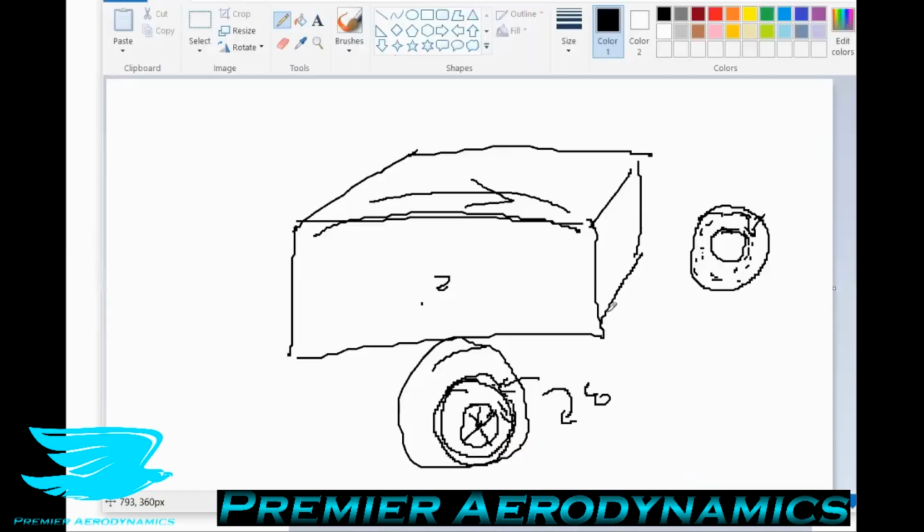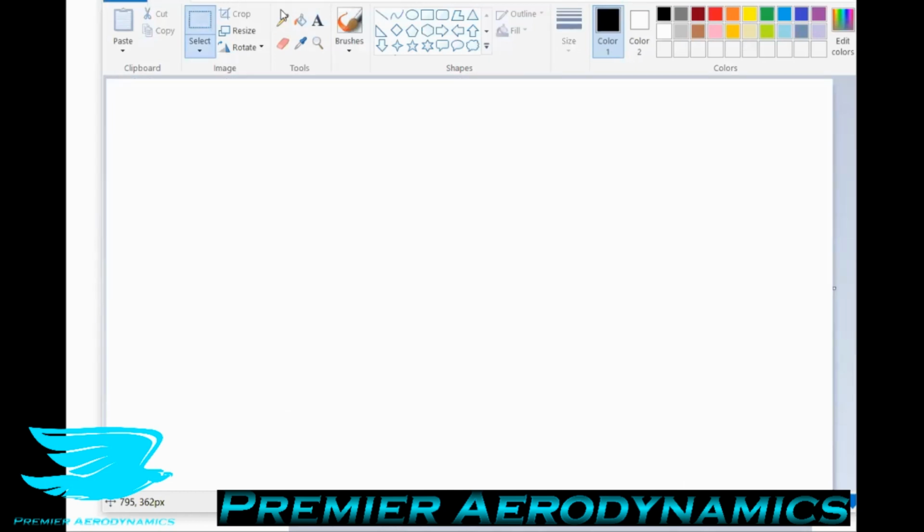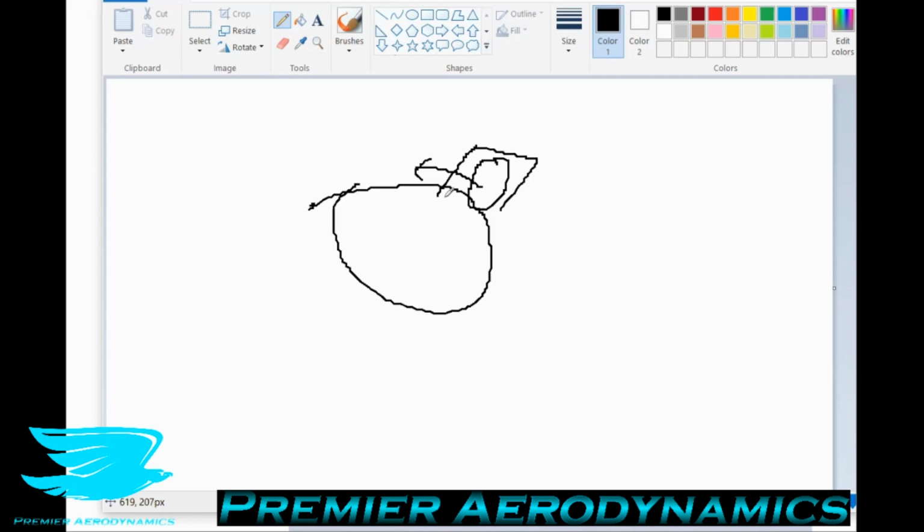So what is this? So far in this podcast, we've talked quite a lot about CFD methods, which it's good to know. So this Overset Mesh technique, what is this? Let's say we have your object. It can be any object. Let's say it's a rock with another rock on top. And this second rock is moving around with respect to the first rock. Well, regular meshes can't really handle this very well. So what we do is we actually make a secondary mesh around just this second rock, and we have the entire mesh around the first rock plus the second rock.